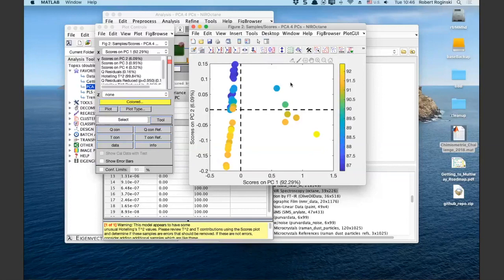Now, for the gasoline with alcohol samples, it's a little bit more complex. In this direction overall, you have an impact of higher octane rating, but the octane rating is going to depend upon the octane rating of the gasoline feedstock that you started with, and also how much alcohol you had added.